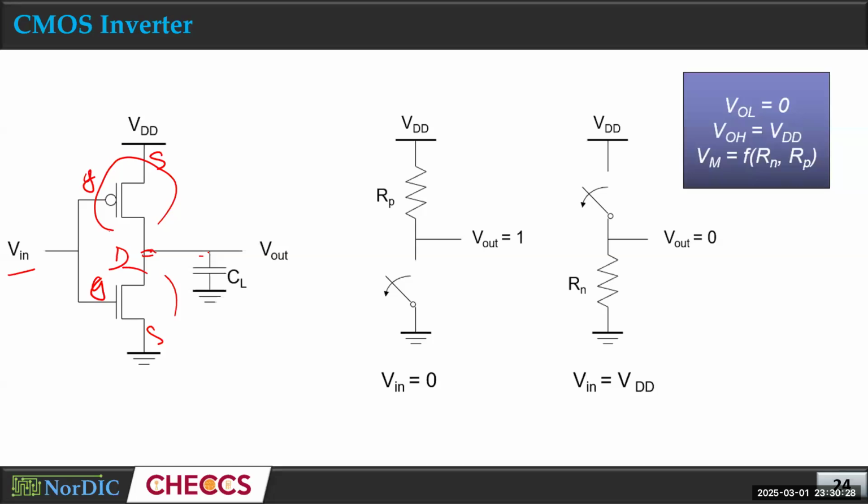When we apply this 0 voltage, we have two combinations, a logic 0 input and a logic 1 input. This is the logic 0 input, 0 voltage. We just discussed that for 0 voltage, the NMOS will remain off, because to turn on the NMOS we need to apply a high positive voltage. So for 0 voltage the NMOS turns off. You can see the switch is broken, so there is no current flow here, I equals 0.